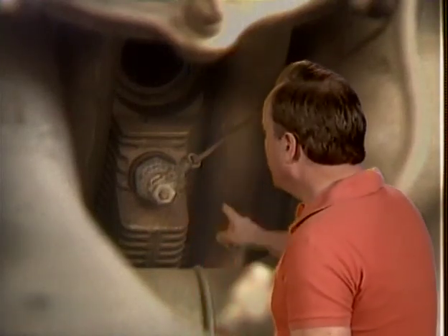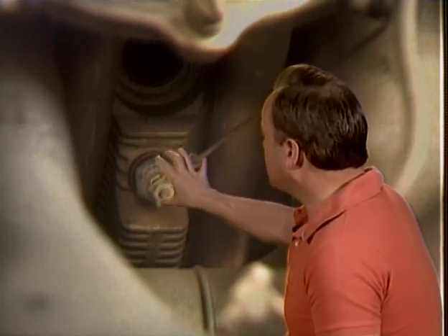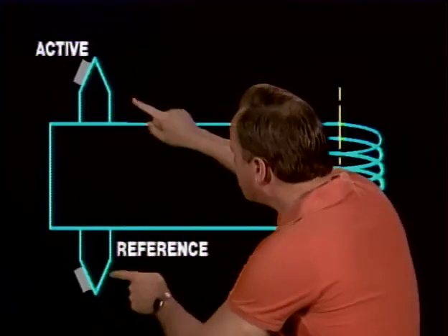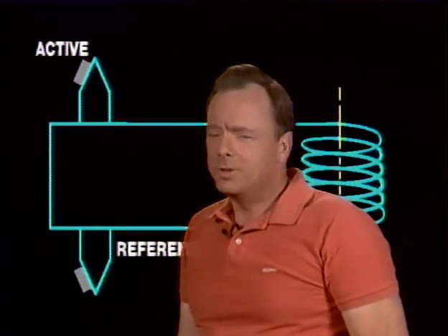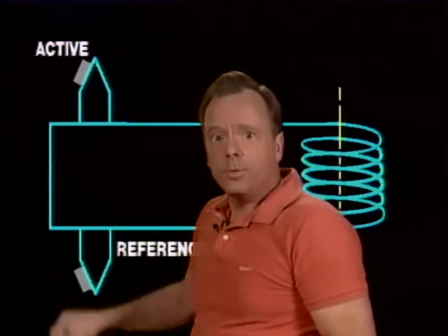All right, the indication of temperature in a thermocouple type cylinder head temperature indicator is produced by current then, generated by the temperature difference between dissimilar hot and cold junctions. And here's a case where you have the hot junction sensing the temperature there in a cylinder head temperature indicator. So they're going to say, okay, what determines the voltage output and therefore the current of a thermocouple type system? And it's determined by the temperature difference between the two ends of the thermocouple. You guys have got this nailed. Now, where would the hot junction be located once again for a cylinder head temperature indicating system? Well, the hot junction typically would be located right at the hottest cylinder, and the cold junction be located in the instrument. So you guys are getting the questions nailed on this.